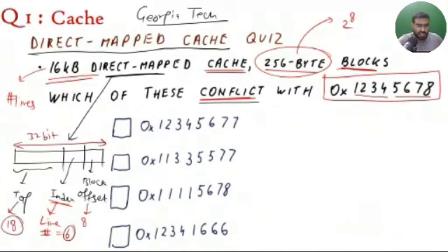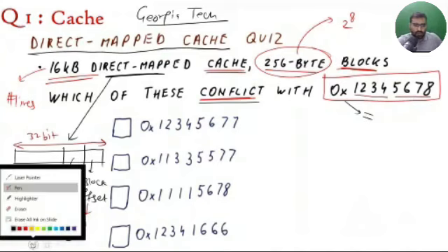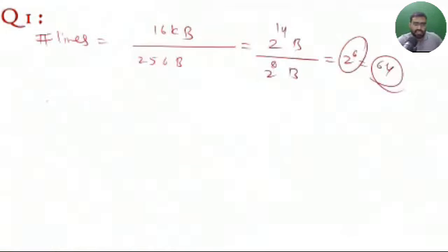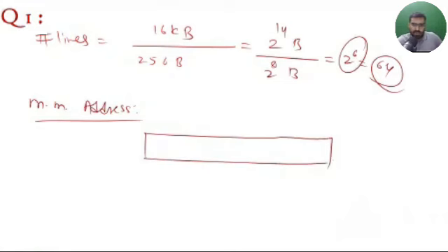So you can notice what the block number is here. Can you tell me what the block number is in this? Whatever cache scheme you have, the block number will always be determined like this. You have the main memory address, and whatever cache type you take, set associative or direct mapped, this part is always going to be the block number, and this is your block offset.